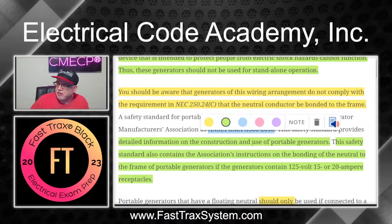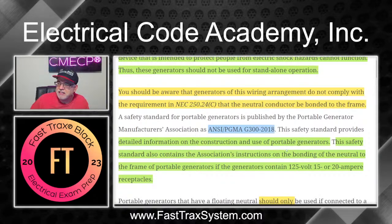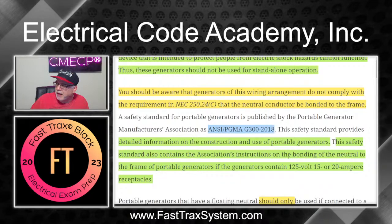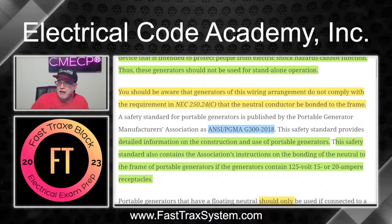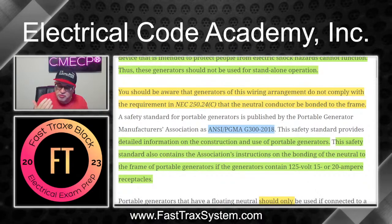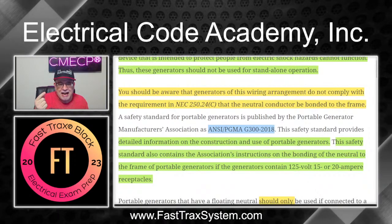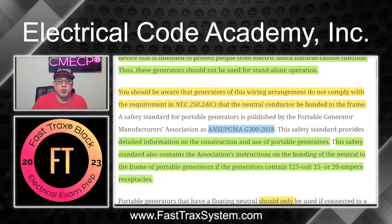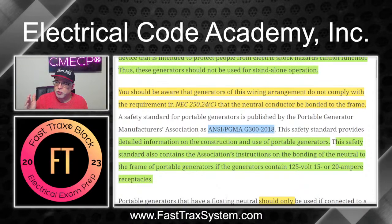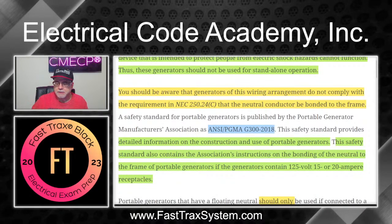Now, in that standard, it's going to give you various details of the construction of a generator. And it's also going to tell you the instructions on bonding the neutral to the frame if the generator has 15 or 20 amp 125 volt receptacles. Then it's going to say, hey, if you've got these receptacles, guess what? I'm going to need you to bond the neutral to the frame of this generator. Okay, so that's where you're going to get all those instructions.